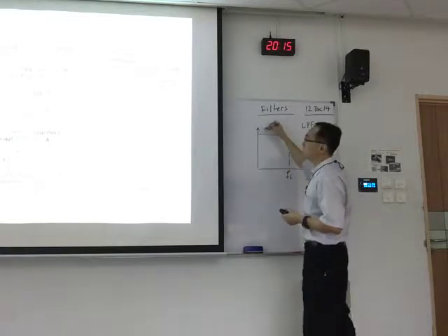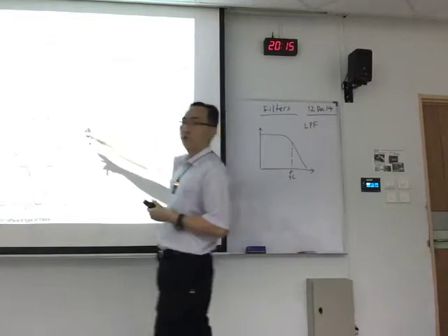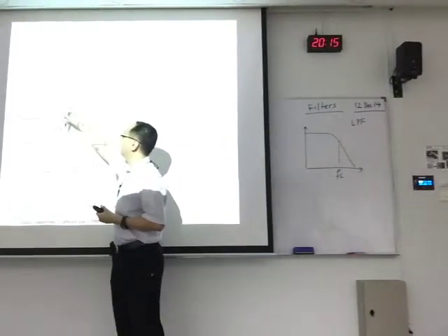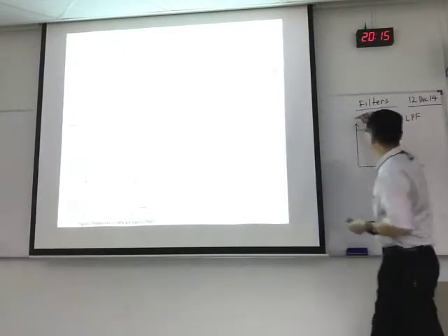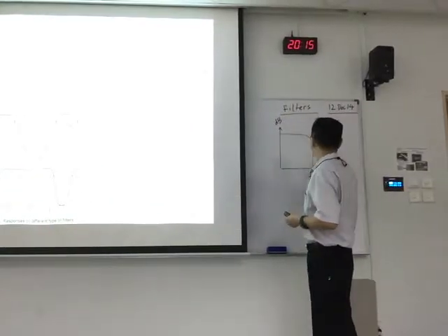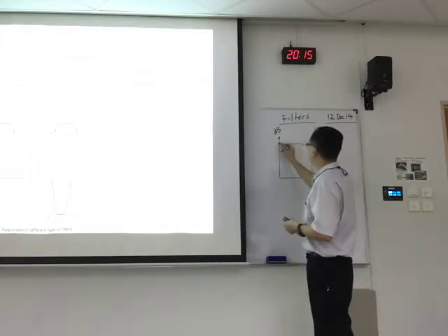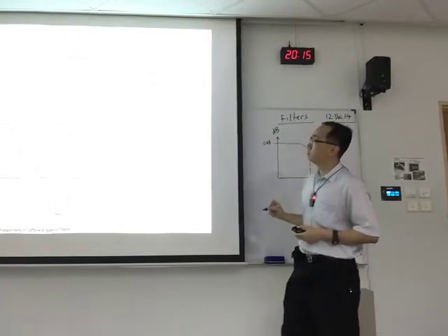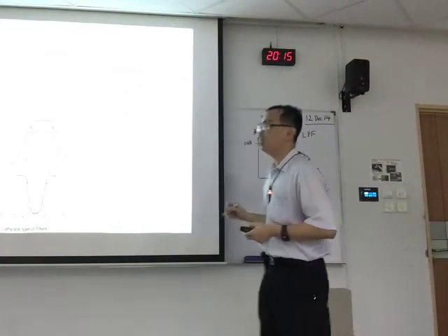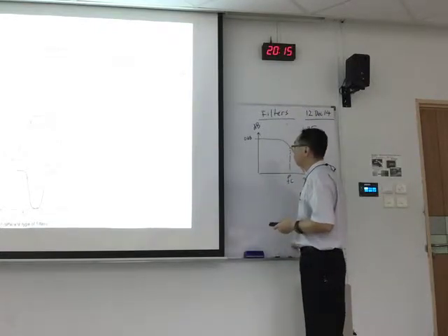Now how does it roll off? If you look at the plot, the waveform, this is the gain in decibels versus the frequency. This is the dB gain, and this is the frequency plot. You will notice that it's always 0 dB here. I'll explain why 0 dB: 0 dB means the filter itself has no gain.